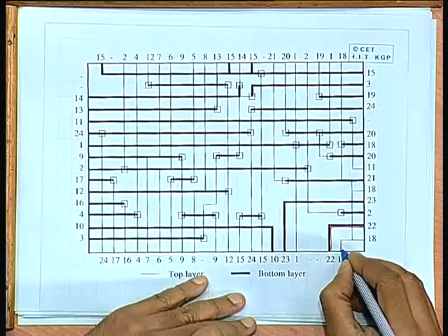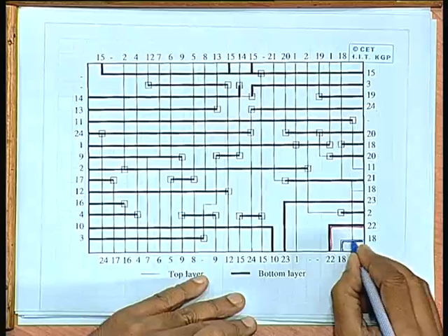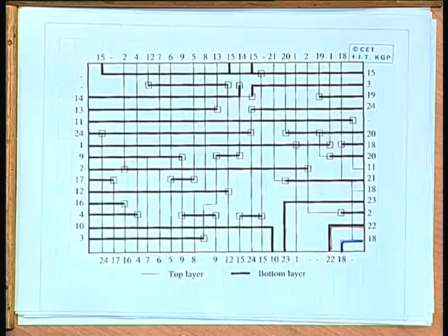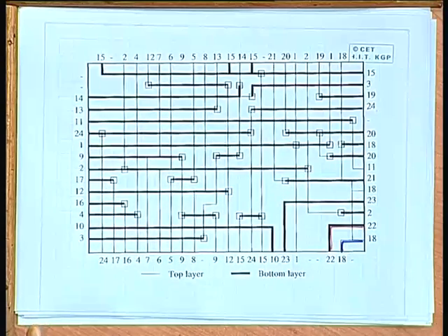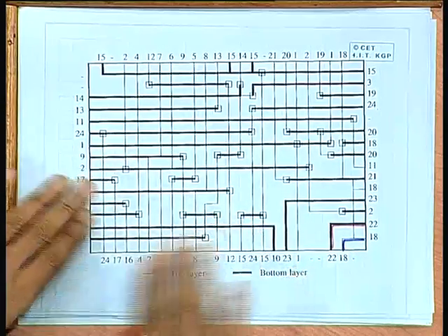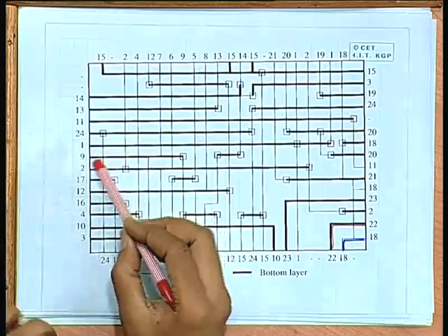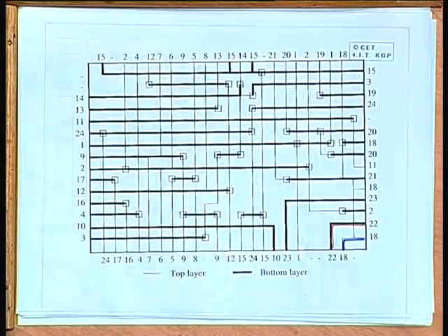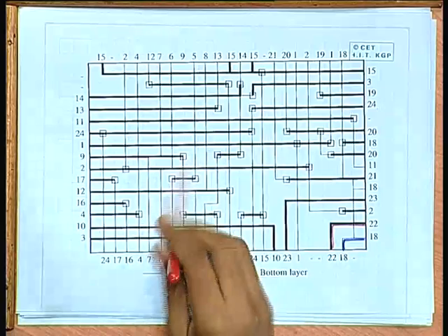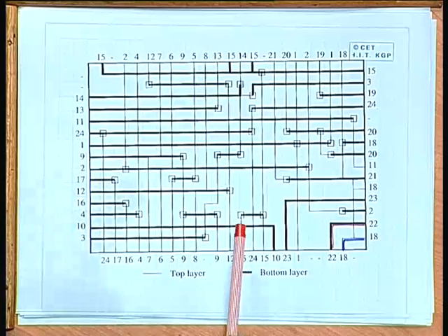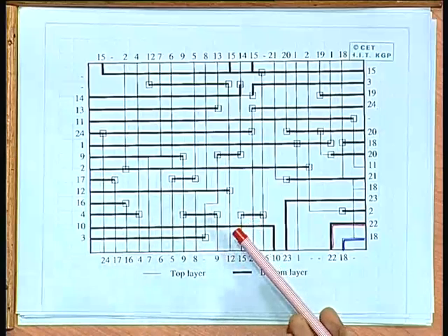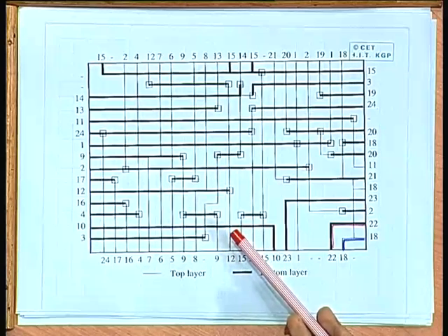Similarly, this on a different layer but on the same track, same meaning layer. So, there is no concept of separate horizontal and vertical layering here. Although this is a 2-layer solution, the nets can be laid out arbitrarily with any kind of horizontal and vertical segments on any layer. Okay. So, there is no better method available for switchbox routing as compared to this.